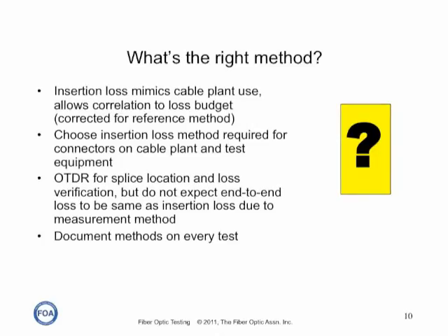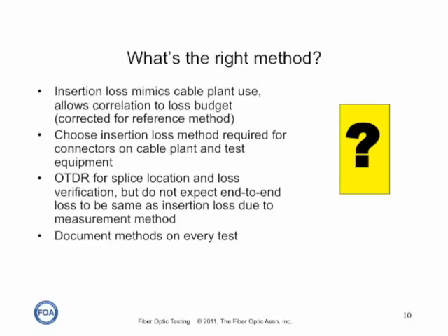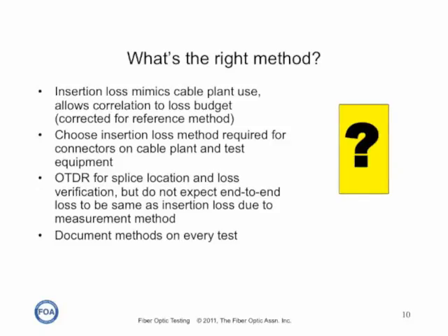So generally speaking, you test with insertion loss to verify that the system is installed properly and will work with your communication system. And you test with an OTDR to verify that you've made splices properly, determine their location, save a trace so that later on you can refer to it for troubleshooting and restoration. So you see, the 5 methods all have their own particular usage and application.